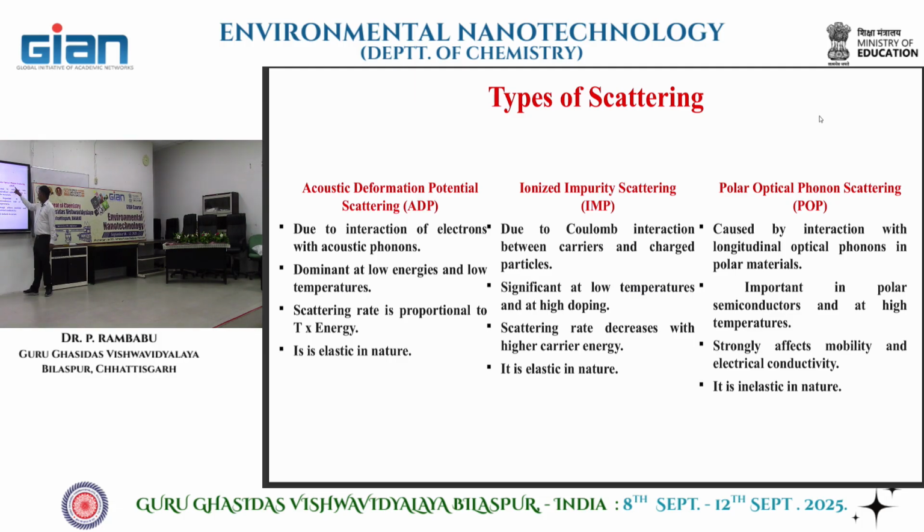And when it comes to polar optical phonon scattering, POP scattering, it is caused by interaction with longitudinal optical phonons in polar materials. It is important in polar semiconductors and at high temperature, and it strongly affects the mobility and the electrical conductivity.